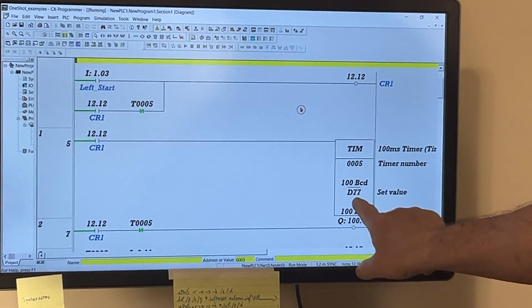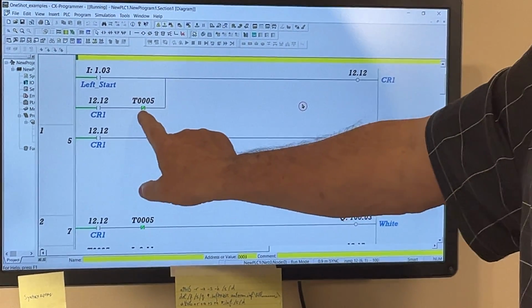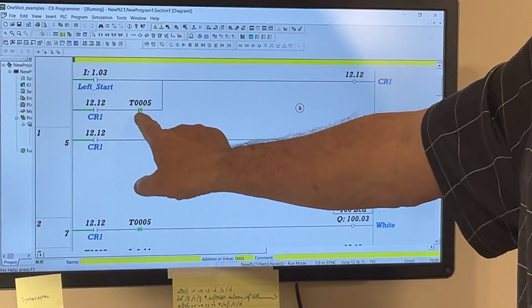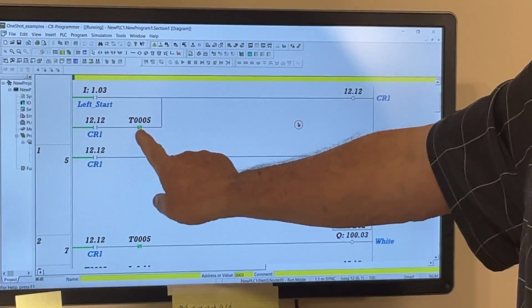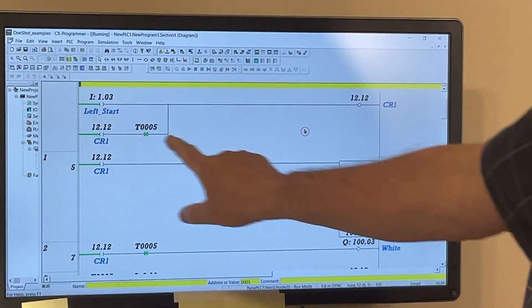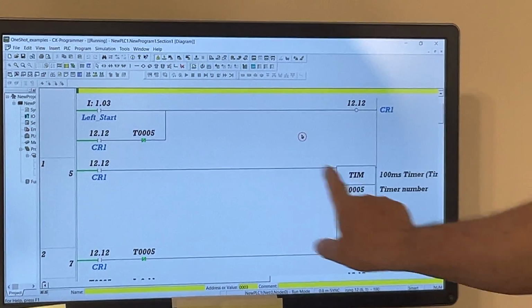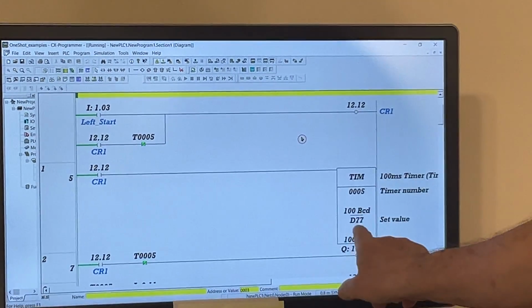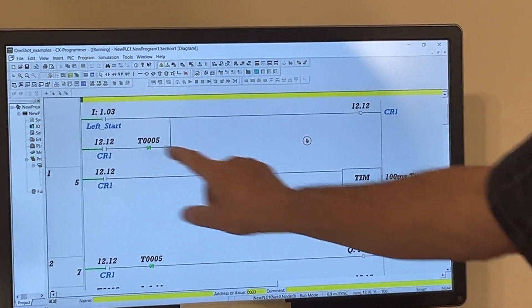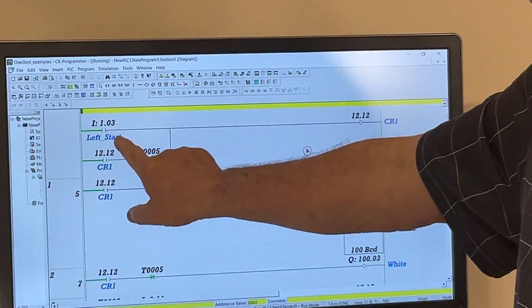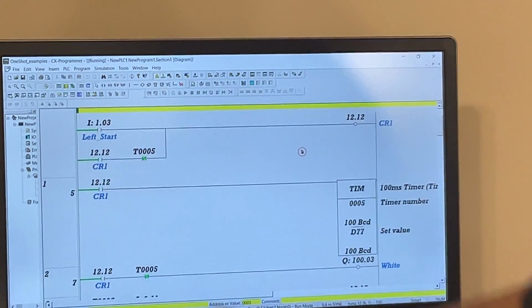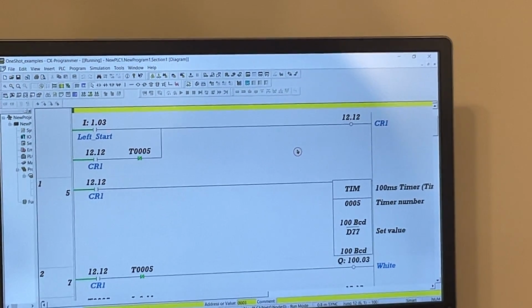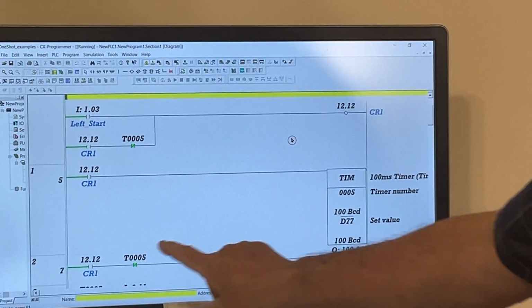Because when the timer is not energized, this contact, as you can see, is normally on. And you can see it here is normally on because it's green, okay? So, in the moment the contact of this timer goes off when the timer finishes counting the 10 seconds, it opens the line here, and because I removed my finger from the button already, it's going to remain off.